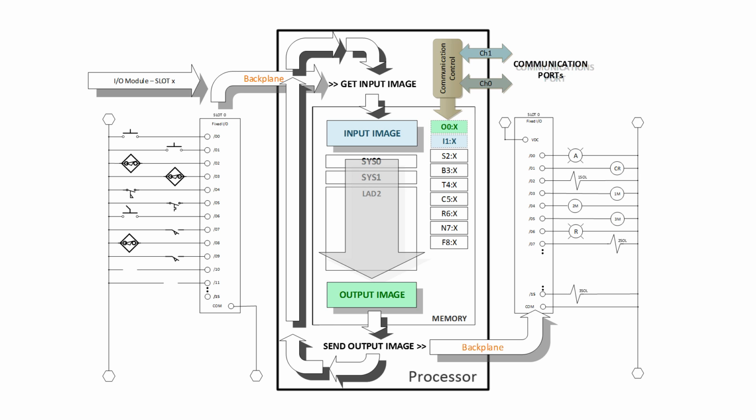It also has input and output electronics. That's a controller. Not all PLCs have it all built into one plastic box. For instance, all ControlLogix and most CompactLogix have a separate processor, and then you plug in the I/O modules. So there's a processor and then individual I/O modules.